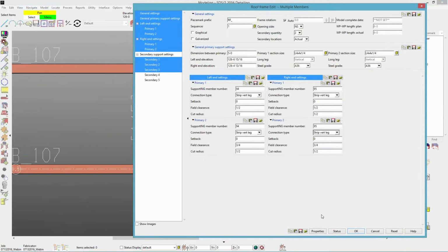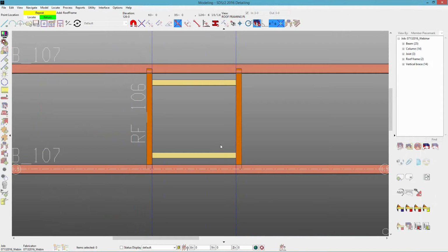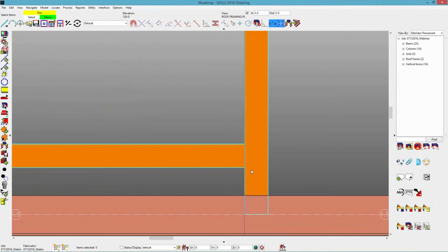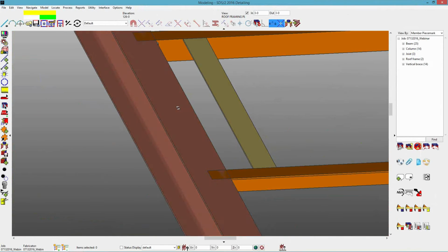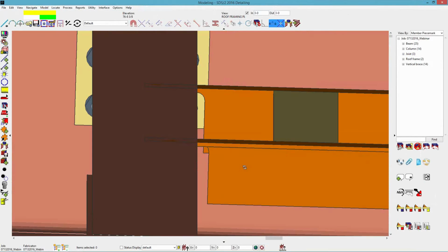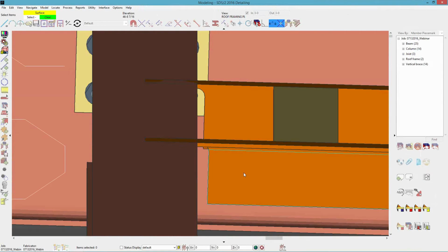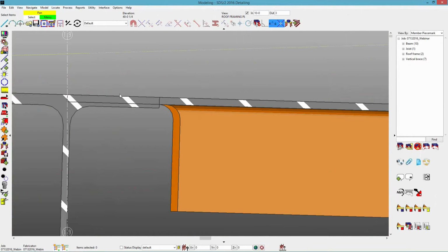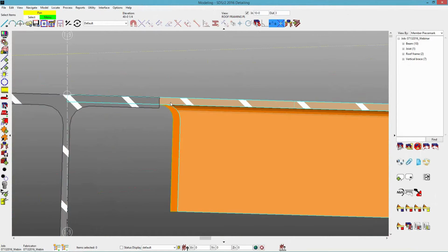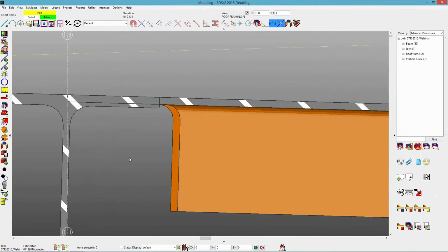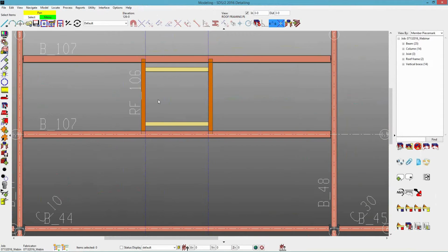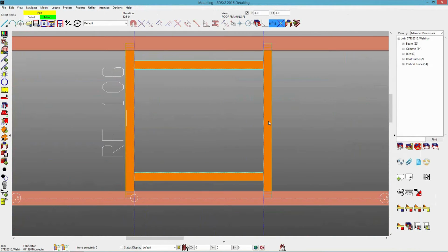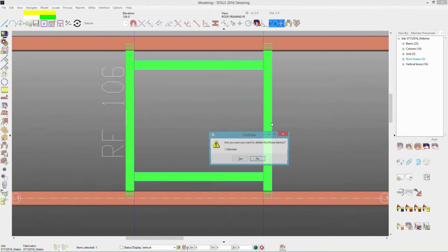Now, with the way that I input this, we're going to have a little bit of an issue. The issue here is that I input that roof frame. Let me snap to the surface so we can see a little better. I input that roof frame right at the same elevation as my beams, so we can see that top leg just runs right through the beams. Well, that can be fixed easy enough if I were to move it up a 1/4 inch, or even easier